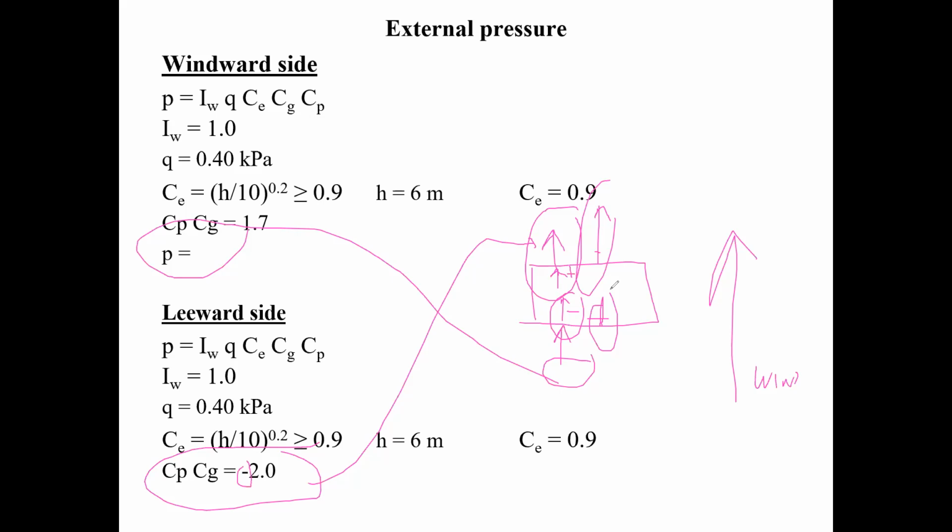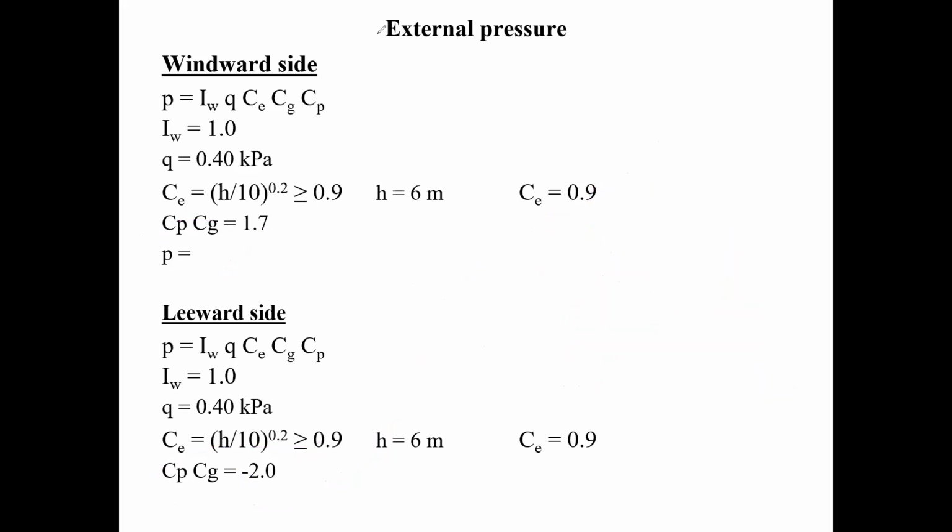Because you don't care if your stud is being bent this way or that way, it's being bent, and it's the highest bending that's going to govern the stud. It's not about which direction it is bending. I don't know if you guys can see that, but that's what this is, okay?